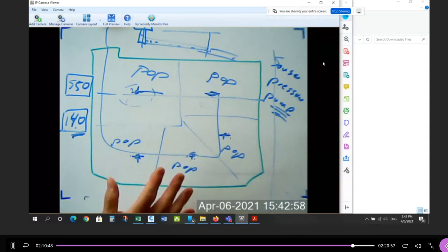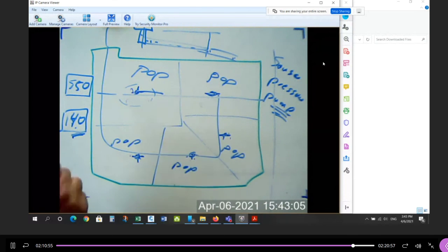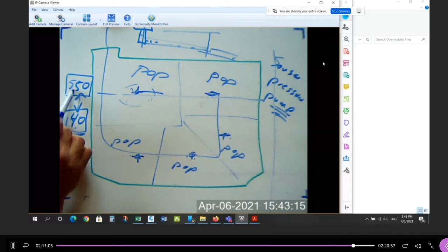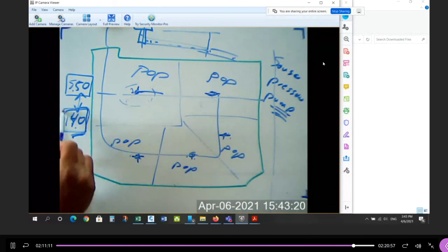When you use the software, it'll show you which pipe needs to be made smaller if there's not enough pressure, or needs to be made bigger under no fire flow based on the maximum pressure. The operating range is here. Typically at maximum or close to the higher pressures at your house when there's no fire, a typical day. And if there's a fire, you still want domestic water flow to each unit or each point on the system, so you want to make sure that nothing drops below. When there's no fire, everything is below 550. When there's a fire, everything is still above 140. And that's the general analysis that happens.